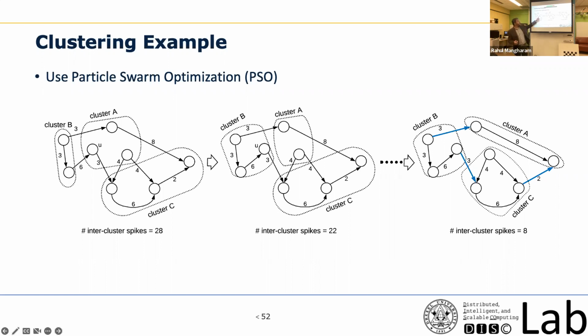The thing is, clusters are formed beforehand because you have to map them onto the hardware. In the compilation stage itself, you have to look at the map, see how many spikes there should be based on your training data set, and then do these cuts so that the cost is minimized. Each of these clusters can then go into one of the hardware cores. But that's not all.